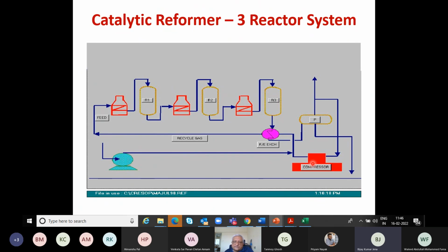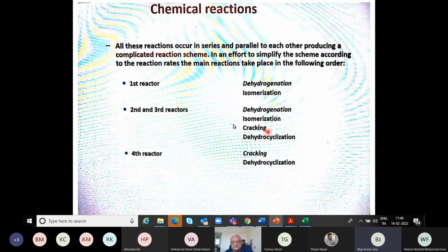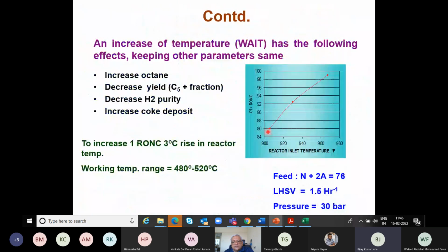And for the rest, in terms of higher space velocity, the volumetric flow rates go up as you go down on pressure. So the pressure drops in the reactors go up, and the size of the reactors has to be different if you are designing this unit for a low pressure operation. 3 bar and 30 bar is an order of magnitude difference. At 30 bar, the reactor sizes will be much smaller compared to when you design it for 3 bar, because there's a 10 times expansion in volume. If you remember your ideal gas law, PV is equal to nRT.